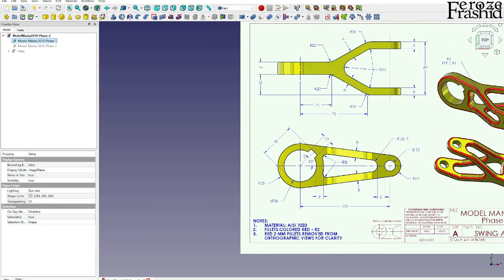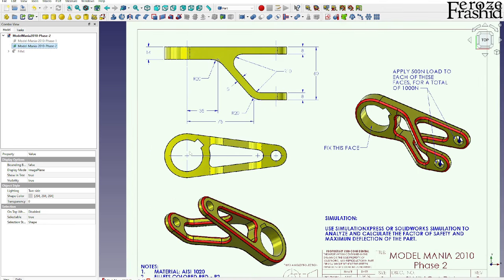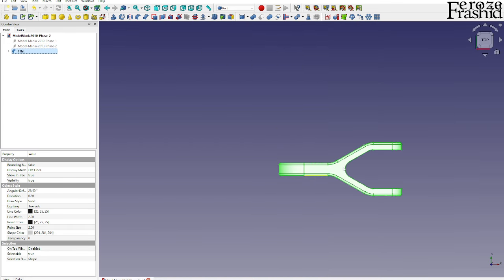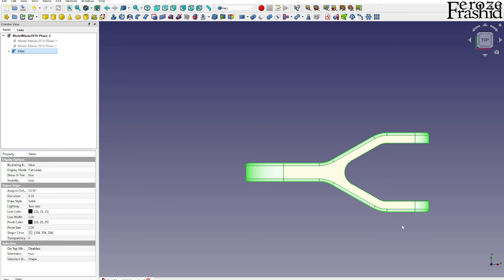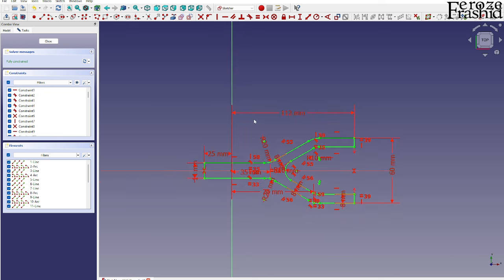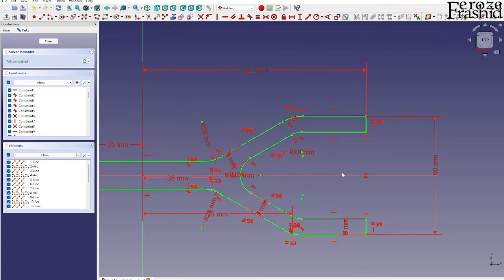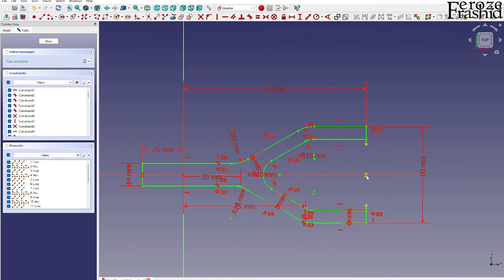So this front image is the same. That tells me this gap and this hole are the same location. So the only thing I'll have to worry about is making this arm straight and pushing it downward. And we can do that easily by changing the top down sketch. All we have to do is take this and take that away and make it a straight line. Okay. And I will be taking the symmetric constraints off.